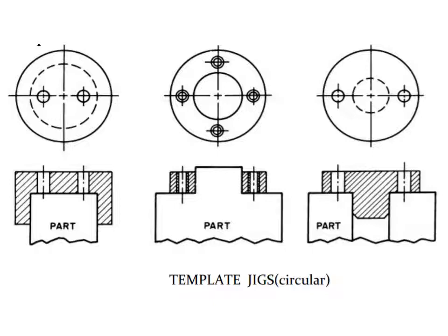And according to the shape of the part, the fixture can be modified as shown in figures second and third, where the part shape is a bit different from the first figure. In the second figure, the part is having a projection, whereas in the third figure, it is having a hole at the center. And accordingly, the fixture is designed, and it is used for making holes according to the requirement of the part.